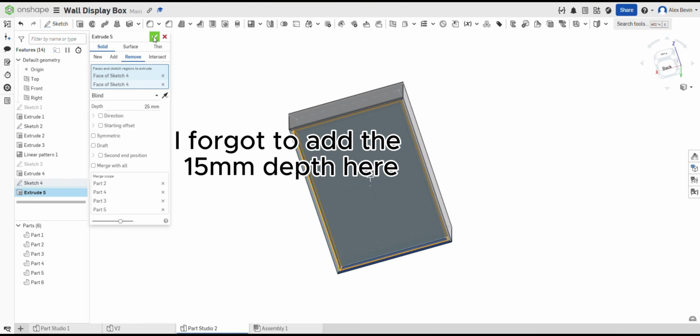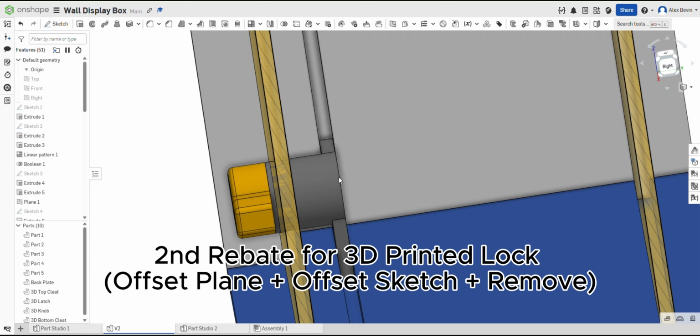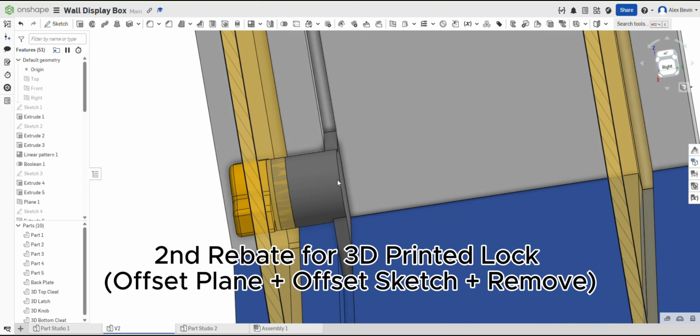Now you should have a clean back rebate pocket, 8 millimeters of border thickness, and a second rebate for the 3D printed lock: offset plane plus offset sketch plus remove.